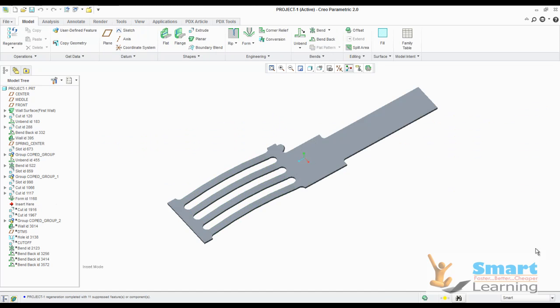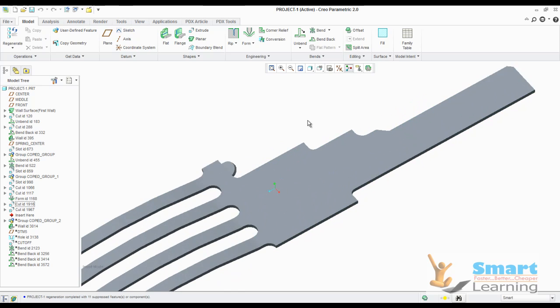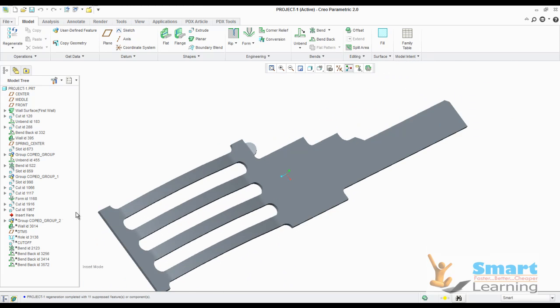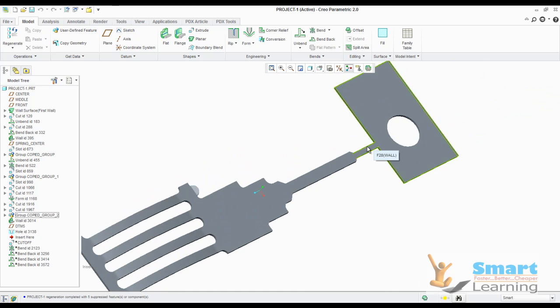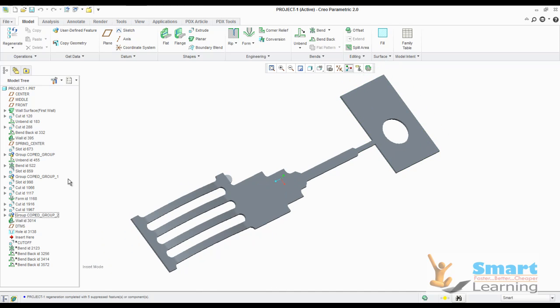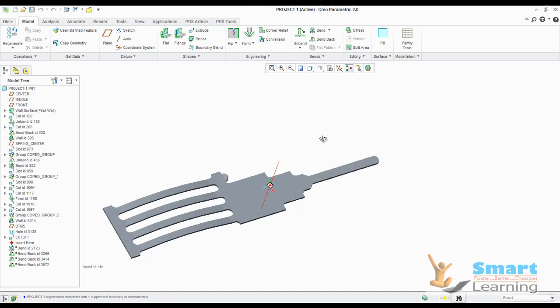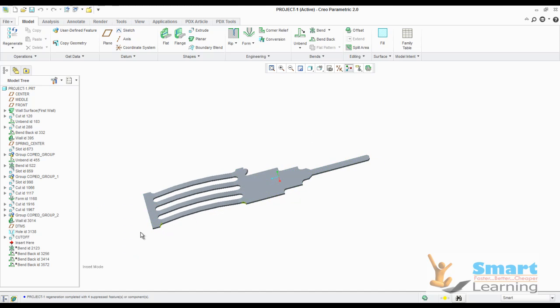After doing these operations you can cut out this particular typical section by using the profile, and after that you can perform these typical operations by attaching a wall, and finally we'll be doing a final cutoff here, whatever cutoff you need to have, and after that we'll bend it.